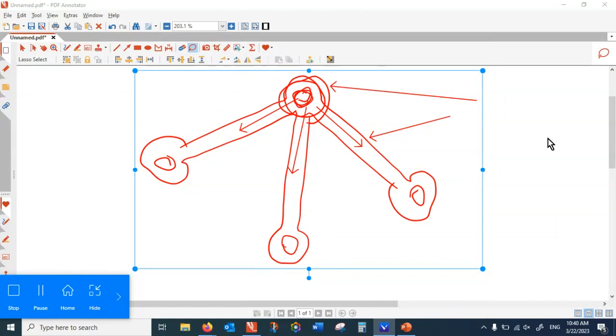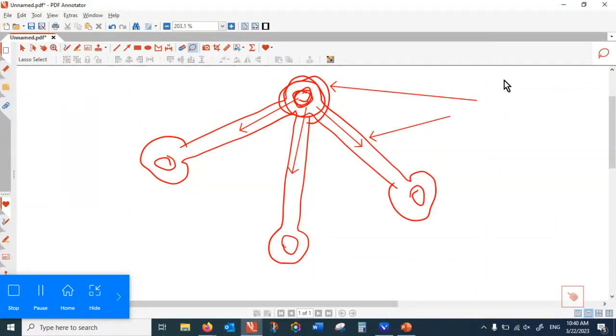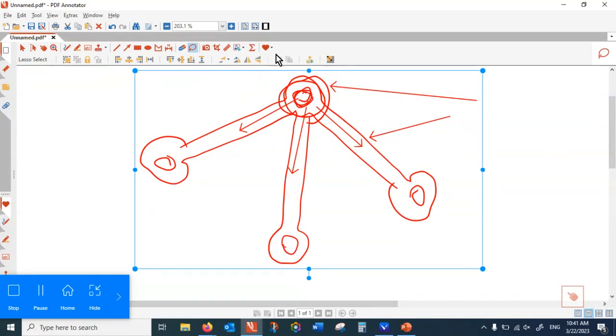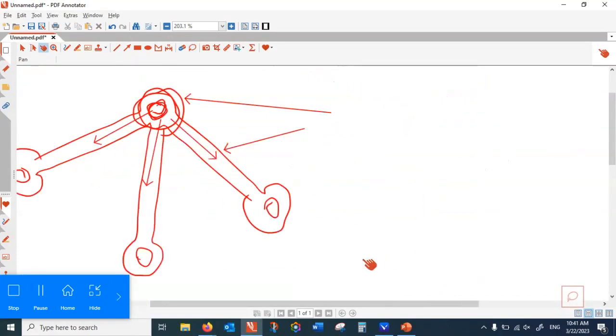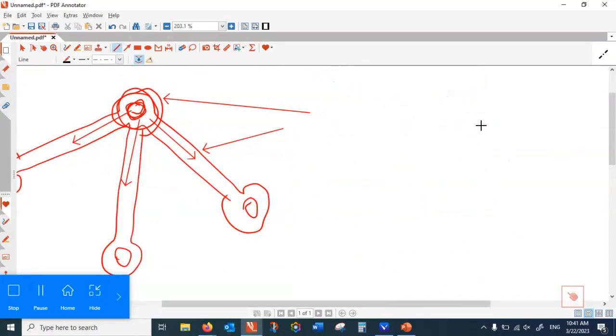Yeah, when I apply method of joint, what happens? This method of joint is a free body diagram. That's an enclosure which is cutting through the members. The forces are internal, but the minute you cut them, you have to expose them. So if I cut this one, what happens? There's a simplified shape would be like that, right?